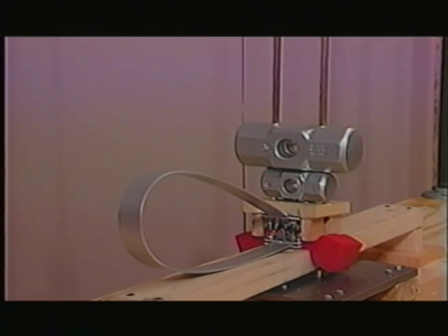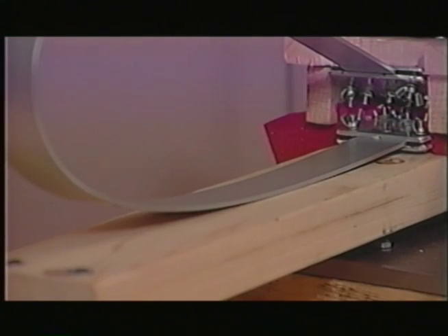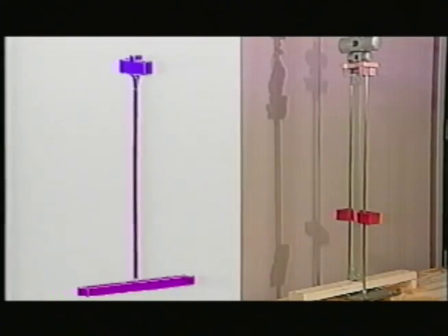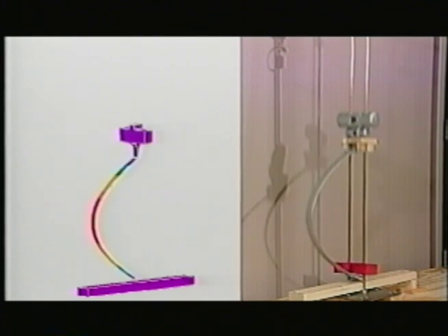Note that in fact, the column has indeed buckled as predicted. We do have a very large deformation. And the bar has contacted the floor, forcing it into the final shape. Let's do an instant replay in slow motion. As you can see, the AccuPack event simulation and the actual event match closely.